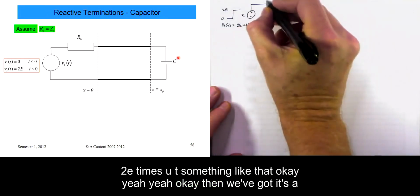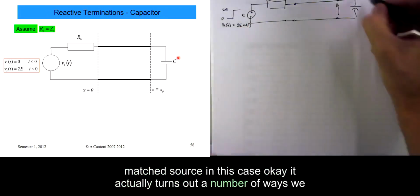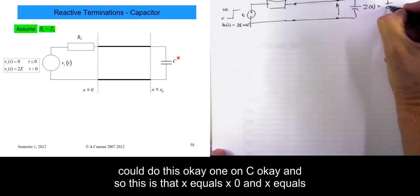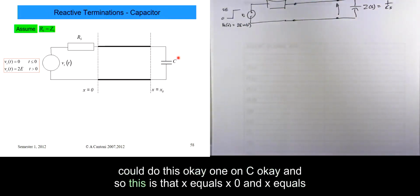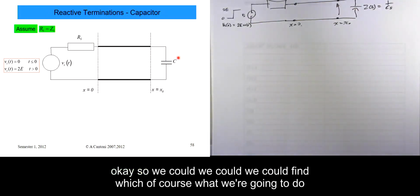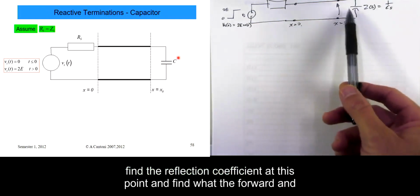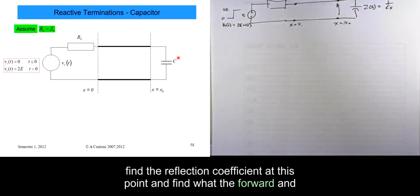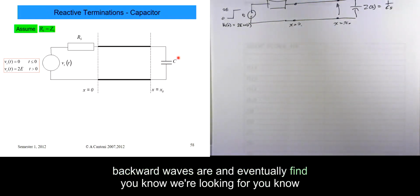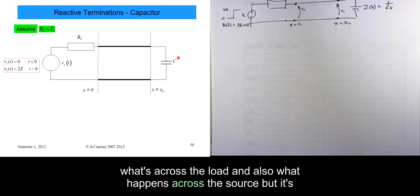Then it's a matched source in this case. It turns out there are a number of ways we could do this. We have 1 on C here, at x equals x0 and x equals 0. We could find, which is what we're going to do, the reflection coefficient at this point, and find what the forward and backward waves are, and eventually find what's across the load and also what happens across the source.